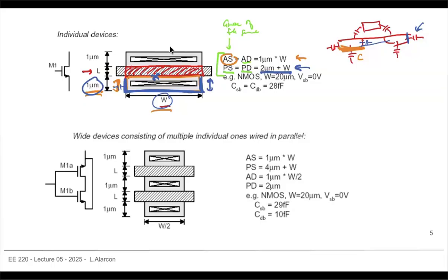So if you do have a wide transistor, then as you probably imagine, it's better to put in multiple fingers instead of one very wide transistor. For one, you reduce the resistance that you see on the gate. So you break it up, then I have less resistance, and the signal will travel half the distance. So you actually improve this by quite a bit.